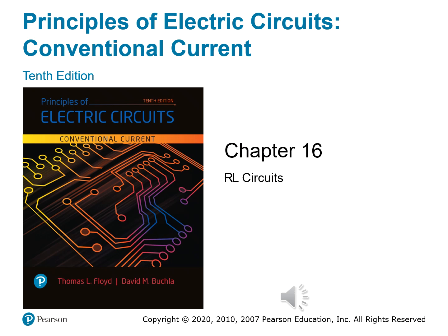In this chapter, we'll explore how inductors and resistors work together in transient and steady state conditions, how to calculate time constants. If you recall, tau is equal to L divided by R, inductance divided by resistance, and understand what they mean physically, how to analyze current and voltage curves using universal exponential models, and how to apply these concepts to switching circuits, to filters, timing circuits, and a whole lot more.